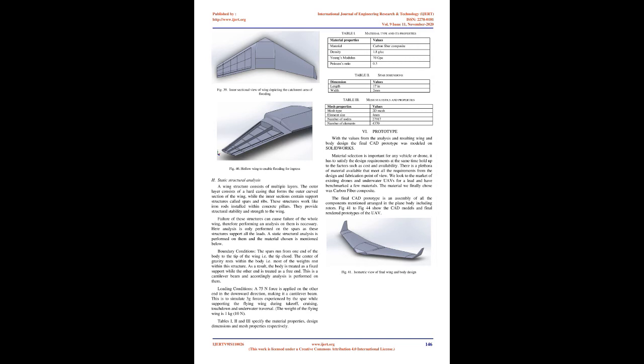1. CM vs alpha. As seen in Fig 34, the curve has a negative slope. The value of the angle of attack where the moment is 0 is also a good value for the angle of attack for the wing. 2. CM vs CL. At 0 moment the lift is positive. This confirms the prerequisites. Fig 35 shows the graph plotted between CM and CL.